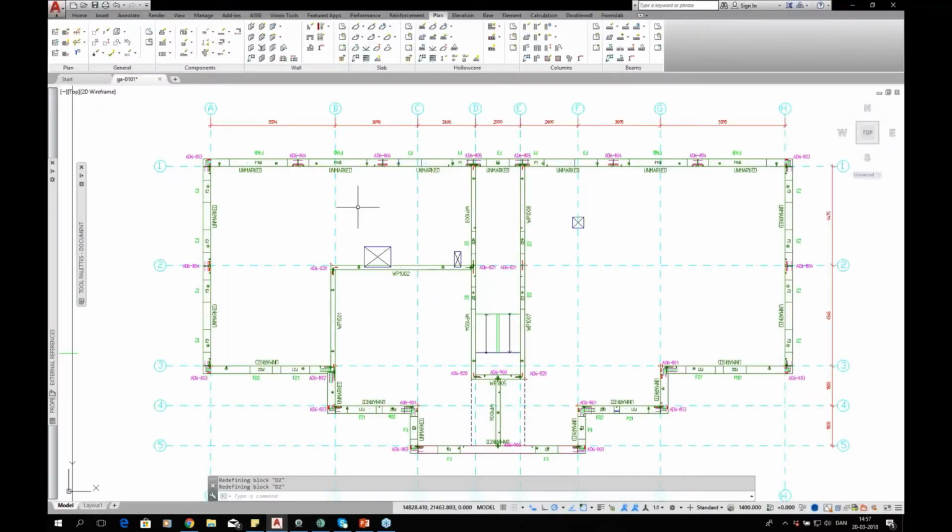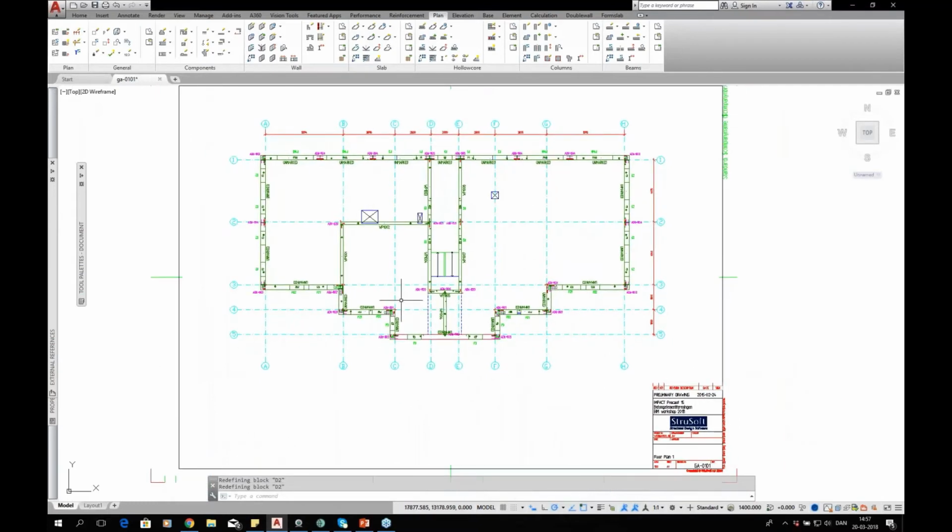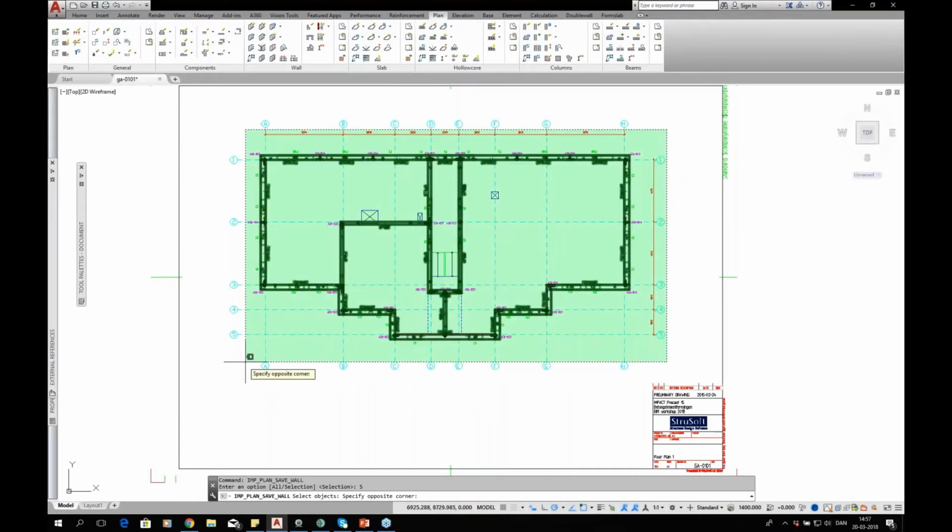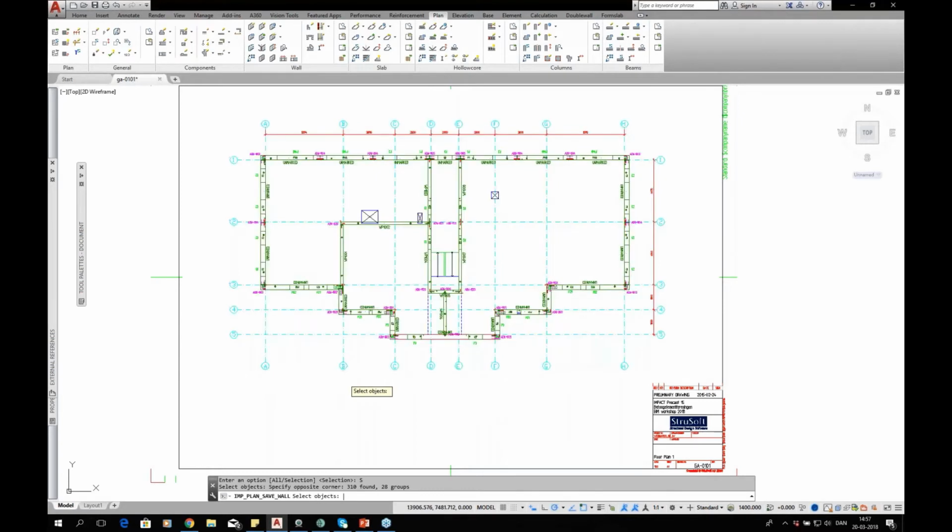Of course, I want to do the same thing with the sandwich walls. I can pick which walls in which order I want to save them, or I can say save everything. If I wanted to save them, give them numbers, and say, well, I'm doing an erection plan later anyways, let's just have the system save it, and it can decide when. It just has to start with sandwich wall 1001.